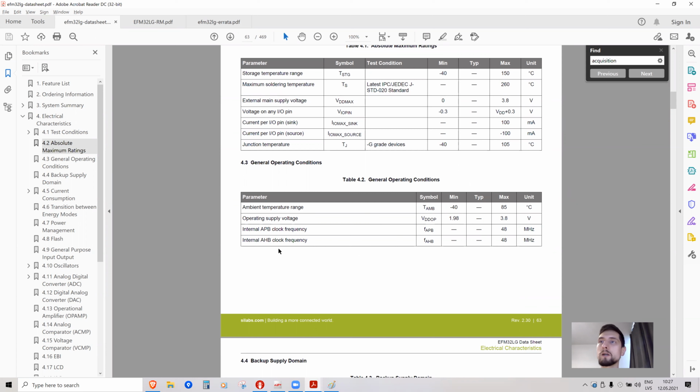All of these DC-DC converters have a temperature control built in. So when the device gets really hot, it just shuts down and cools off. And only after it has cooled down does it turn on again. And so we caught our client misusing our device, putting it in a too hot place. When we told them that, they moved the device to a cooler place, and the device worked for many years. I don't know, I think it's still working.